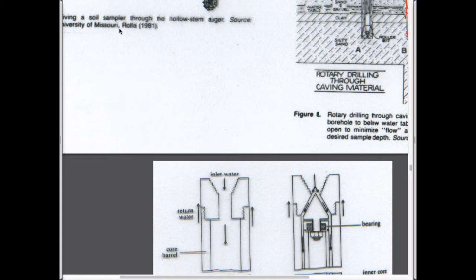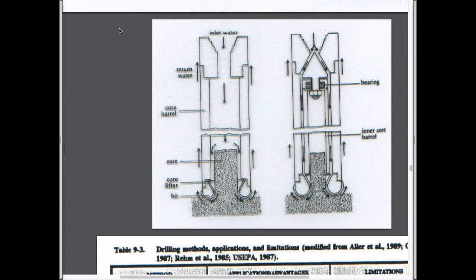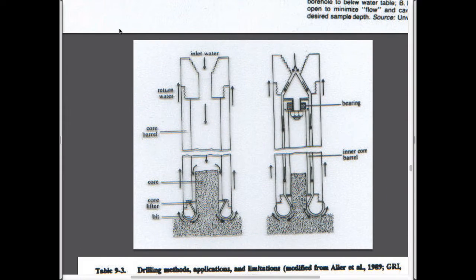Rotary drilling, soil and rock, you get no samples really. You have to take the drill string out to take soil samples, and in rock you don't get any samples at all. And then in pure rock we do diamond drilling, and diamond drilling allows you to take a continuous sample as you drill through it. And so the idea is basically shown here.